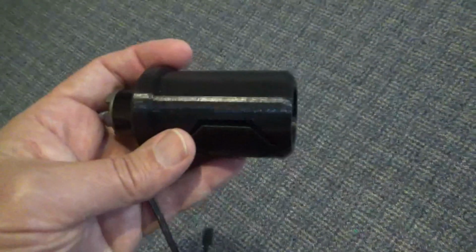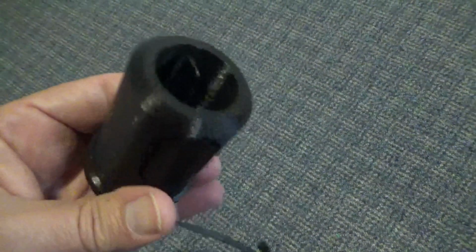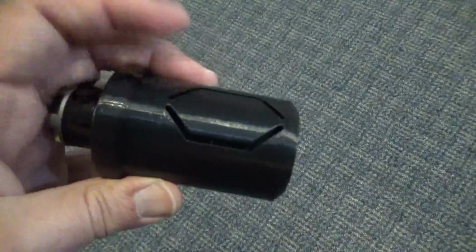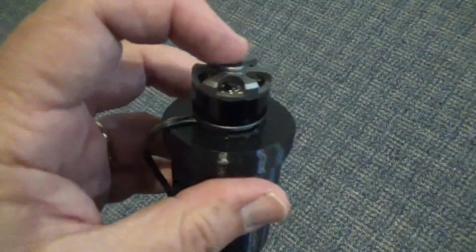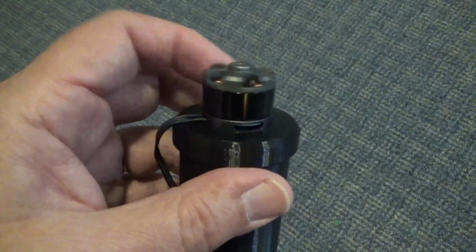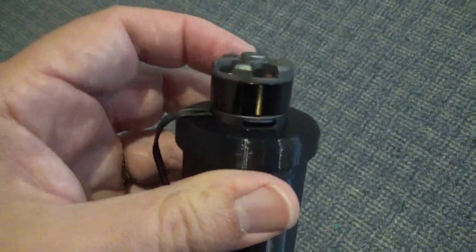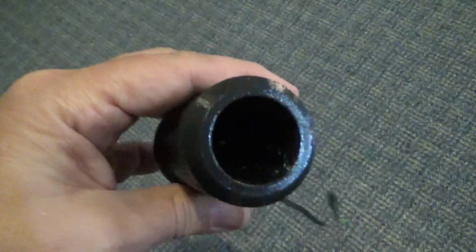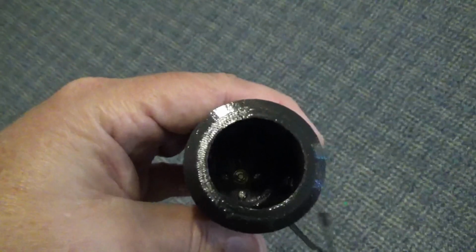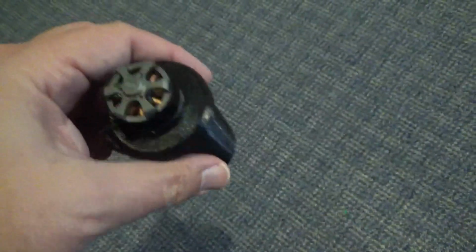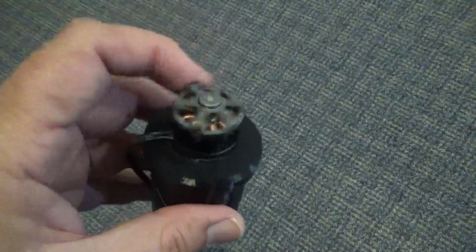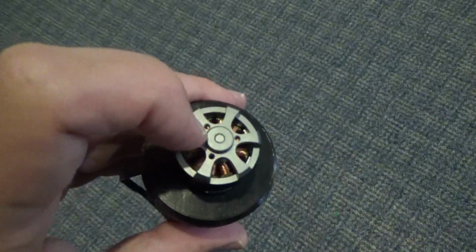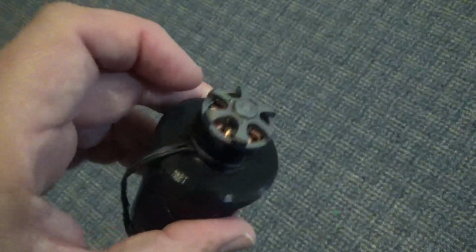This is the base of the wind turbine. It goes on top of a 1-inch EMT tube. It just slides on with some press fit features there. And this is a 2208 gimbal motor, and this is acting as the generator. It mounts to the base with 4 M4 bolts, 8 millimeters long. You can see them in there. And the rotor mounts to this gimbal motor with 3 M3 bolts, also 8 millimeters long.